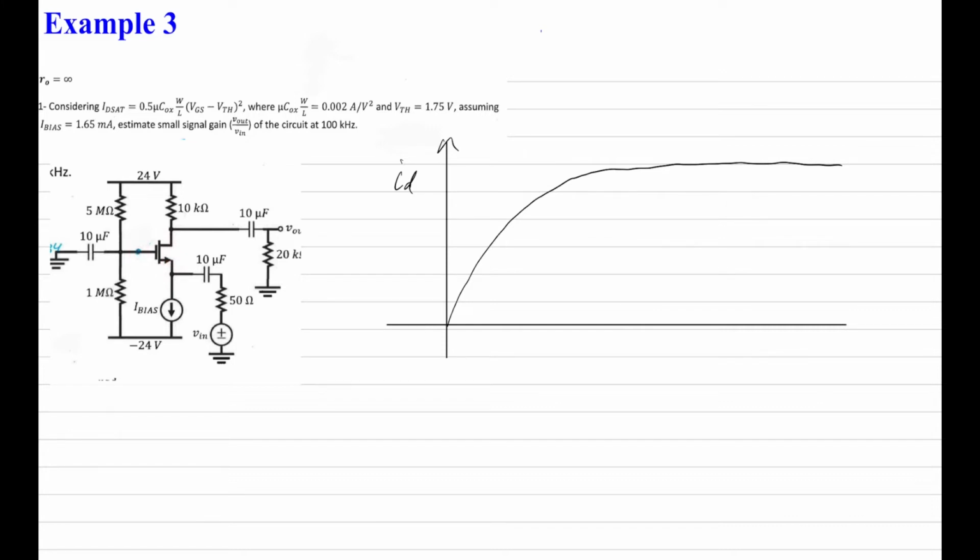The other important principle to remember with a MOSFET is that the current going into the gate is 0. There is no current that actually flows between the gate and the source and drain. All the drain current goes straight into the source, like this, okay?